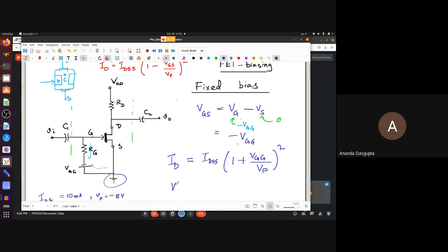Okay. The only other thing that you need is the voltage at the drain, VD. So how much is VD going to be? Yes? VDD minus IDRD. Yeah. You start from the battery here, you know the voltage here is VDD. Then you go down, this current is ID. I should have actually indicated that already because I am talking of ID a lot. So VDD is the voltage here, IDRD is a drop across RD. The voltage at this end has to be VDD minus IDRD.